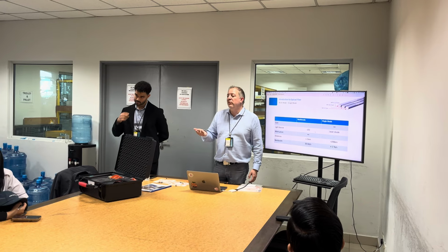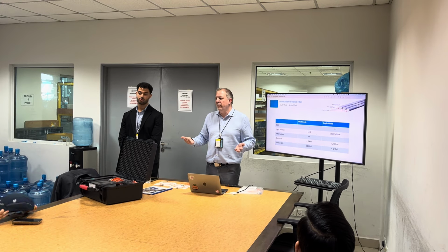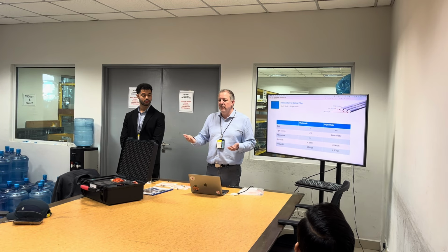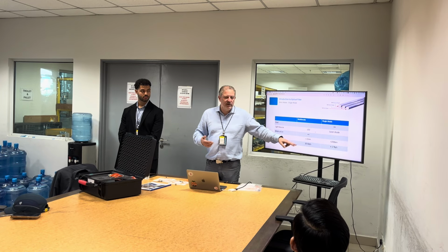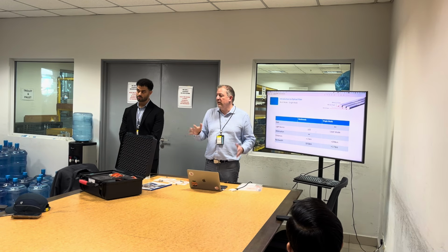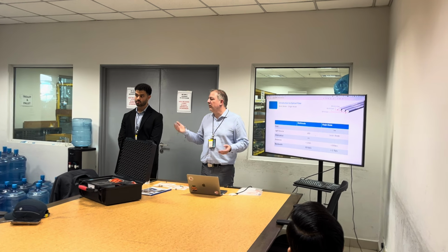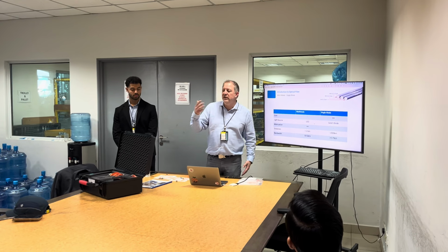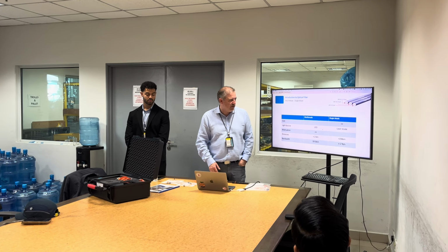Single mode would be mostly for telecommunication, where you really need long distance. On an aircraft, you don't really take advantage of the long distance, but you take advantage of the bandwidth you can transfer, as well as the fact it's not sensitive to other surrounding systems that can pollute the EMC or radio and other systems.